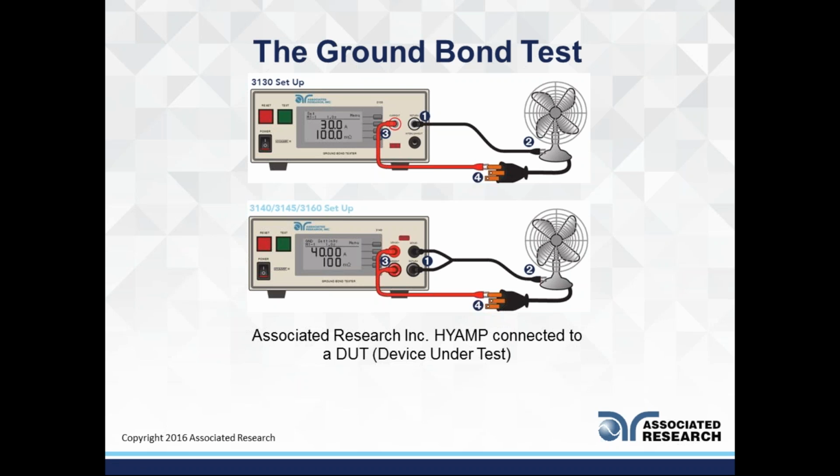So those are two methods. Obviously we have other instruments, 6-in-1, 4-in-1, that also have this Kelvin measurement and offset feature. So it's important, if you're close to that borderline, that high limit of your standards resistance, so 100 milliohms or 200 milliohms, you want to make sure you're utilizing offset features or a 4-wire Kelvin measurement.